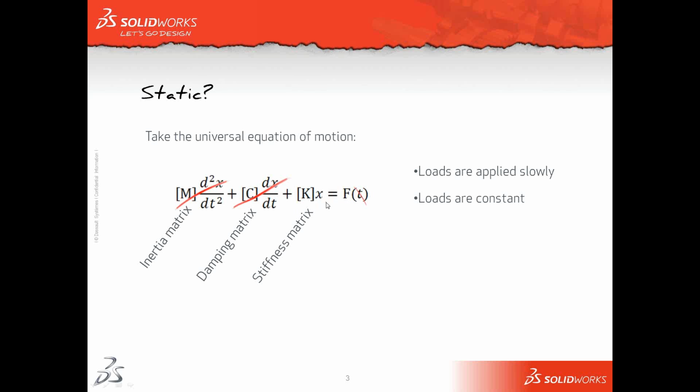So what SolidWorks is going to do is determine the stiffness matrix of our geometry, apply the inverse of that stiffness matrix to our force, and that's going to output our displacements, and then we can go from there to determine the stresses, etc.